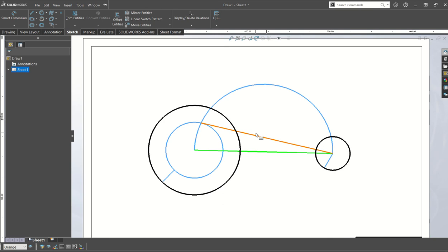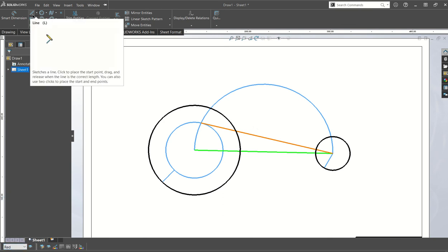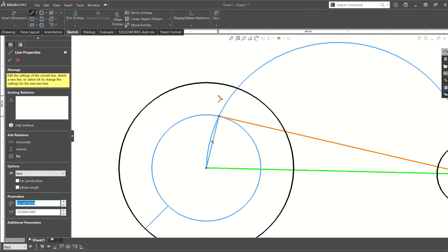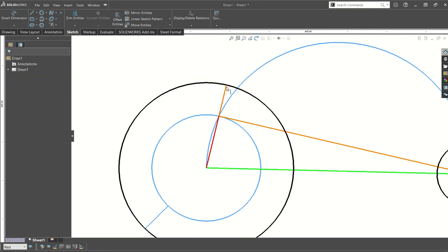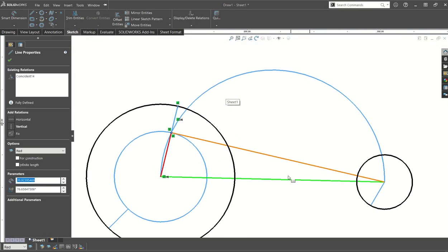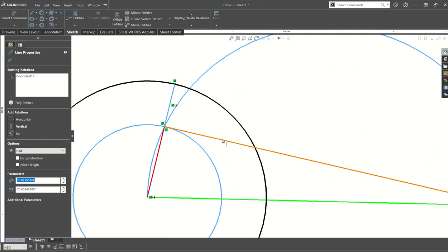So that is a construction of a tangent to that reduced size circle and the point that represents this circle reduced by its radius. Now what I want to do is propagate out these points that are important, the most significant point being where this point here exists on the circumference. So I'll go from my center out to the circumference and propagate out again. If I want to propagate that out again, I just hover over that line and then follow up this yellow line here. Difficult to see on a white sheet, but you can see there that that gives me a line by which I can draw my tangent out here at 90 degrees to, or it gives me an end point at which I can slide out this line with sliding set squares to end up at this point.